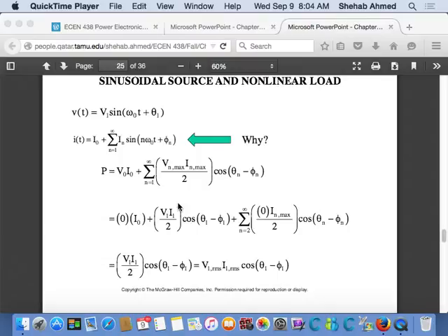The utility will dictate the amount of distortion that is allowed in a system. And if you are causing the distortion, they will tell you to fix it. And there are power electronic ways to fix distortion. Right? So power electronics created the distortion. It's very weird. Power electronics created the distortion, and power electronics can fix the distortion. But it's extra cost. There are power electronic filters that can fix distortion, like a passive filter, but you can also program them to eliminate any number of harmonics, for example, using a certain technique. Yeah, we will discuss that later.